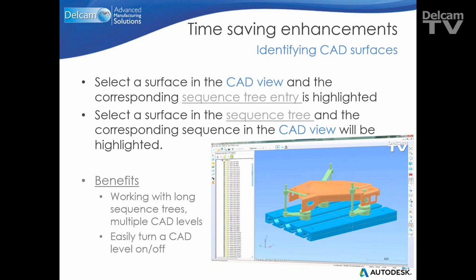By entering the detailed view, the relevant individual surfaces can now be viewed individually. By selecting them on the CAD tree, the corresponding item is highlighted in the graphics window. Alternatively, by selecting the surface selector on the right-hand side from the mouse context toolbar, we can simply click on a surface within the graphics window, and this will then highlight the corresponding surface in the CAD tree.